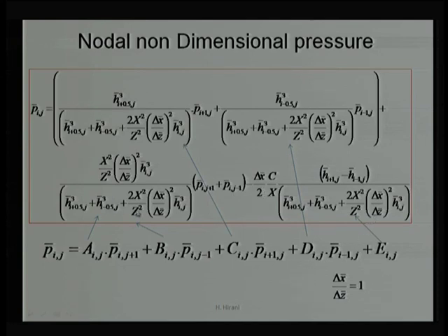Otherwise, all this is a ratio that will be simplified, and the calculation will reduce accordingly, and it is preferable. If we are non-dimensionalizing, we should take equal spacing. Of course, if we are not using non-dimensional terms, or we are not non-dimensionalizing the Reynolds equation, in those situations we should take some other spacing, depending on the requirement and the stability possibilities.